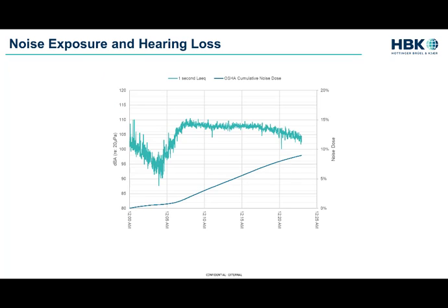When evaluating exposure to dynamic noise levels over a long duration, it is common to calculate an accumulated noise dose over time. Here we have a 23-minute noise sample where a worker is supposedly exposed to noise levels between 90 and 110 dBA. Over the course of this 23 minutes, that worker accumulates nearly 10% of a full day's dose allowance. This is exactly how a noise dose calculator works. It splits up the noise levels into brief chunks of time, assigns a partial dose value to each chunk, and sums those up over a longer duration.